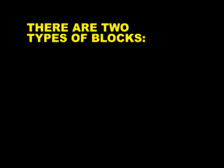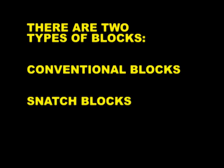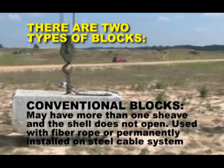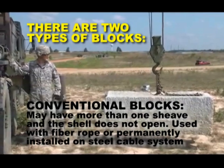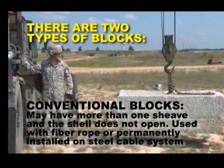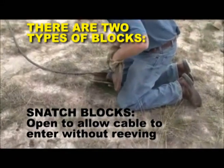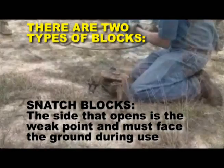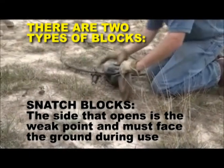There are two types of blocks: conventional block and snatch block. A conventional block may have more than one sheave and the shell does not open. They are generally used with fiber rope or permanently installed on a steel cable system. A snatch block opens to allow a cable to enter without reeving. The side of the snatch block that opens is the weak point and must face the ground while in use.